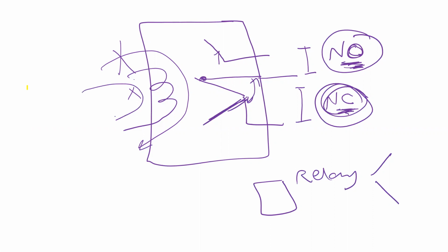And once you energize it, the open is going to be closed, and the closed is going to be open, okay? Sometimes it depends on the circuit, on what you want to do, on your application. So in some applications we need normally open, and in some applications we need normally closed, okay? I have almost finished explaining what the relay is and why it is useful.